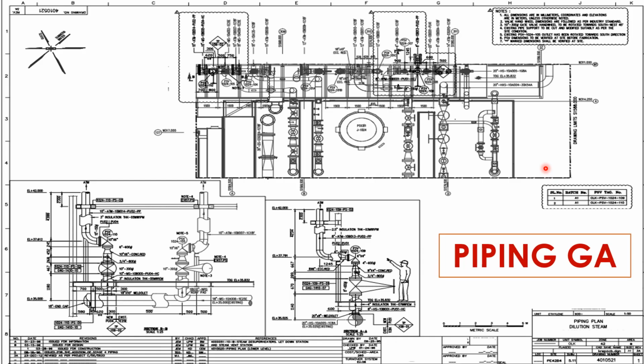So now let's go to the normal piping GA. We have seen multiple samples where it shows the north and the details of the entire modifications, I mean the layout in a particular area in plan, and the details are given more in elevation views and everything, right? So here you can also see the equipment and the existing nearby pipings and whatever structural arrangements over here, those also will be there.